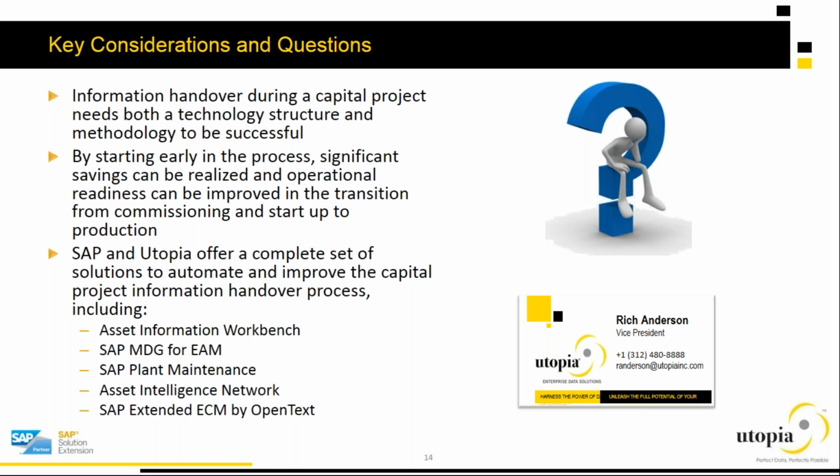Yeah, and the reason that's so important is because the data that we're talking about that exists in SAP plant maintenance, their equipment information, maintenance plans, spare parts that are required in order to maintain that information, all of that data doesn't start life in a spreadsheet, right? It doesn't start life as a master data record in SAP plant maintenance. It typically starts life in another system or in a document. So it might start life as an equipment spec sheet. It might start life in a PLM system. It might start life in a P&ID diagram.